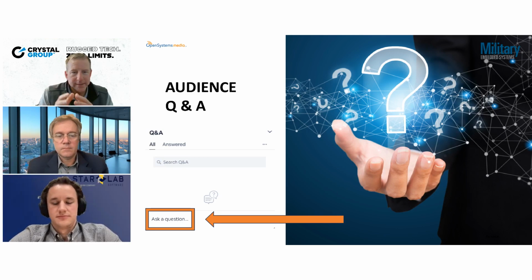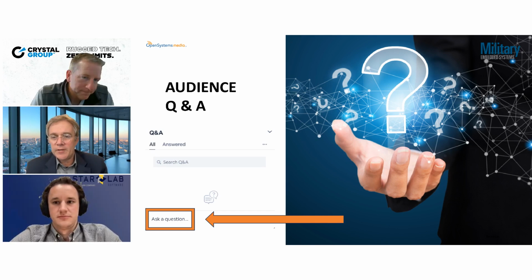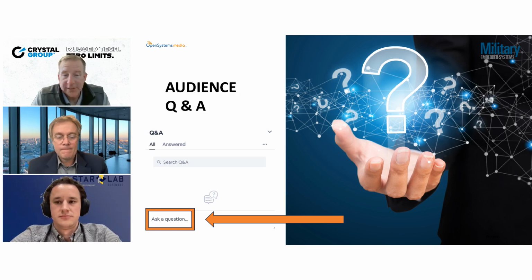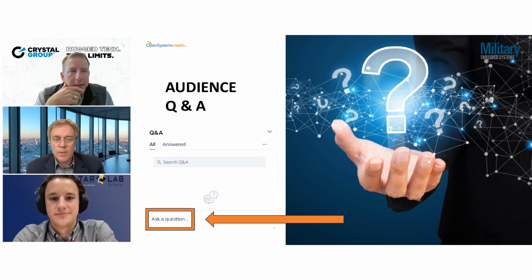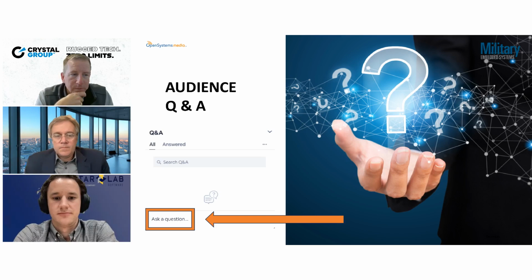There's another question here that kind of follows up on that. What are the techniques that you use for ruggedizing COTS technologies? I mean, I guess taking commercial stuff and making it live in a military environment, right? Sure. I already covered a couple there around machining for thermal and vibe in terms of the chassis and whatnot. Another couple of techniques: there's definitely a lot of coatings you have to apply to the boards, whether it's conformal coating or otherwise, to ensure that you prevent as much as you can the dust, fog, salt fog, that kind of thing.